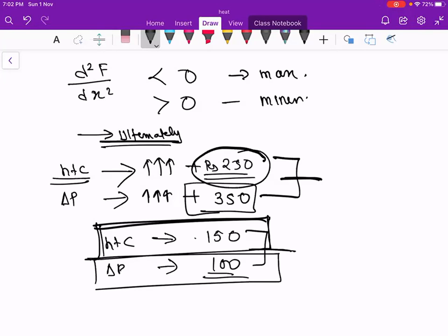So you want to increase the reflux ratio. Increasing the reflux ratio is good, you are increasing the purity of that substance, but your load on the condenser and reboiler is going to increase.